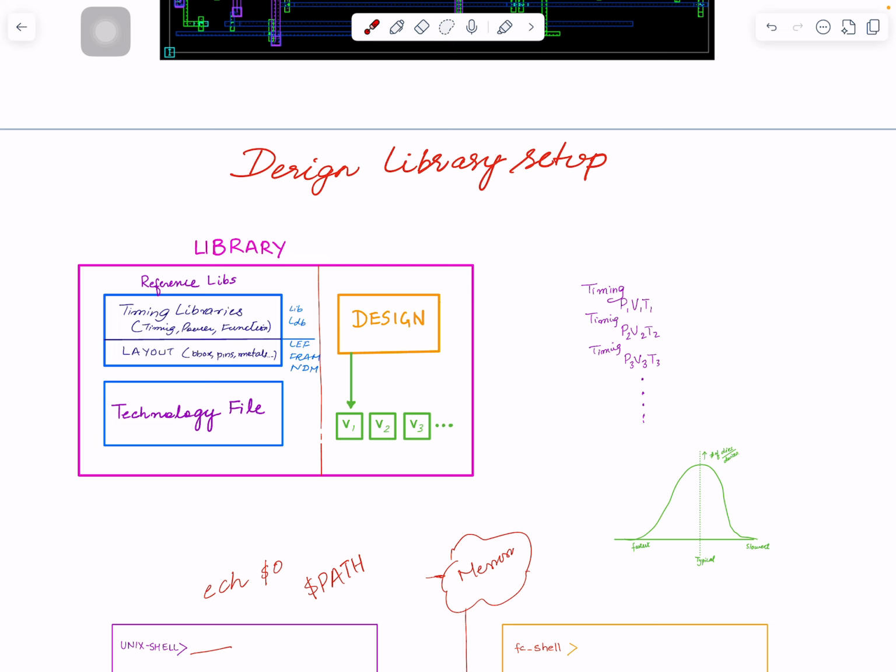that actual drawn metals might be a little different than the metals that you expected, okay, and those things will create different characteristics in your front end, which is the transistor, and back end, which is your interconnect, and those can have different implications on the current through the chip, and that means it can make the chip faster or slower. But before silicon is available, you don't know if a transistor will be slower or faster.